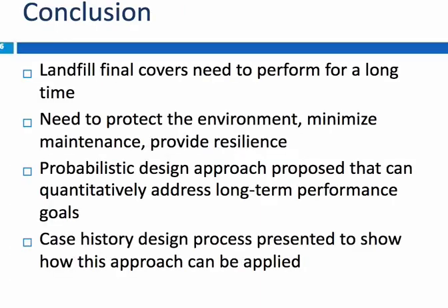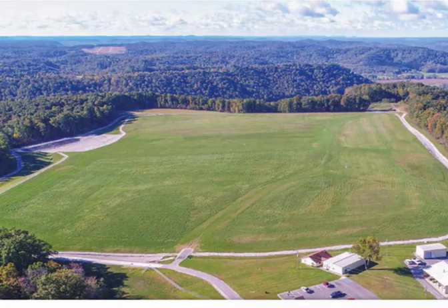Thank you, Kevin. Perhaps a final question for you. How has the final cover performed since it was constructed? So indications that we've had from the site, and they do have a fairly rigorous monitoring program out there where they're walking the site regularly and looking for deformations. To my knowledge, no major deformations have been noted. However, the plan is, should they get major deformations, they are going to fill those with soil so that they continue the runoff regime that they want to have for this final cover.